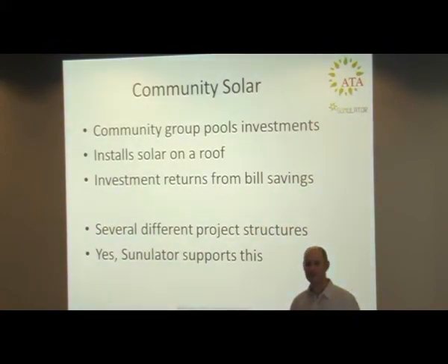They don't have the money to go and do it themselves, or they don't want to do it themselves and pay that money up front. And you also want them to have a fairly constant electricity consumption. If they're only using electricity 2 days a week, then for 5 days of the week it's all going out to the grid. So the more constant their consumption is, like a water treatment plant or a retirement village or something, the better it is.